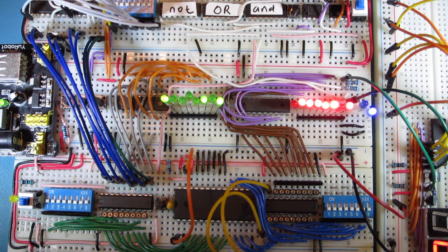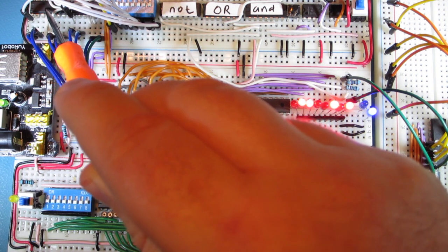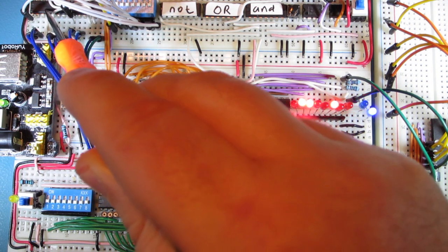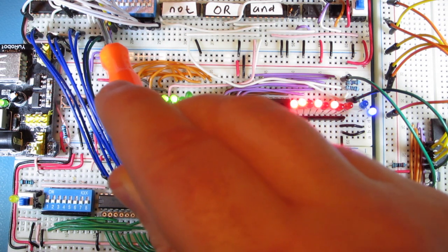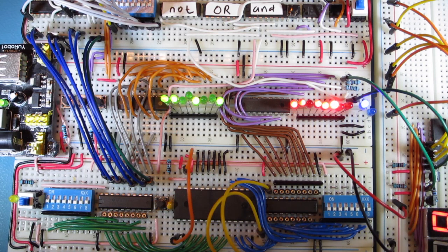The two chips are connected such that if the lower significant bit chip goes over 16, so 1111, it then clocks the most significant bit counter accordingly. The clock is fed into the count up function, and as you can see from the little LEDs on the address bus, that seems to work okay.